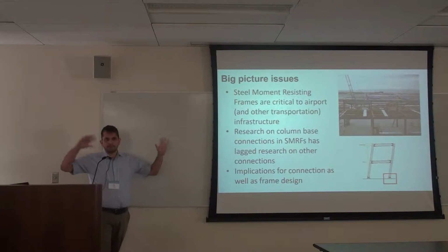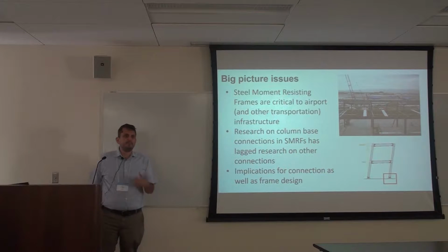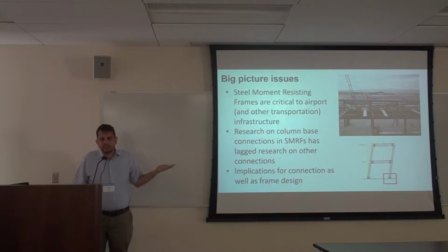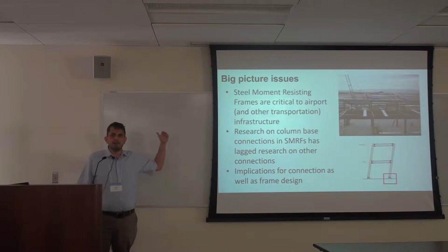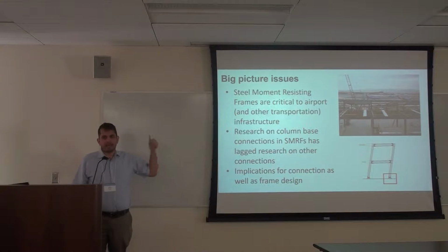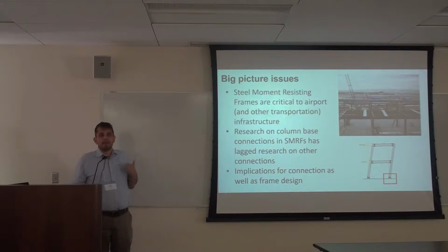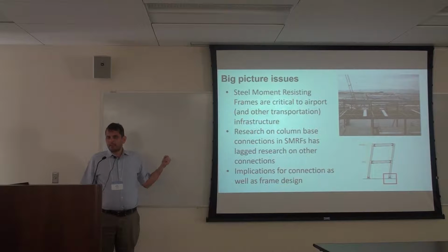From a 30,000 foot view, why is this important? Why is this important to PEER? Steel moment frames are important generally, but if you think about transportation structures, airports specifically, almost every single major airport on the West Coast has a steel moment frame in it, like LAX, San Francisco, Oakland, and that's mainly because you get these large, clear bays. So these systems are inherently very important to the transportation infrastructure.